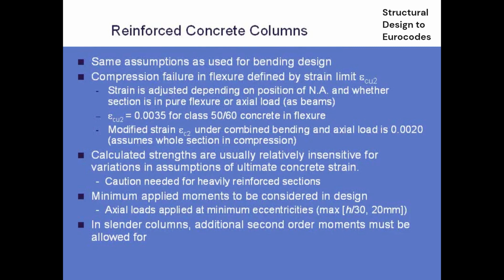And the other thing we have to take into account, obviously, is slenderness. If the columns are slender, then we either have to add in some slenderness extra moments, or we do a nonlinear analysis to include that.